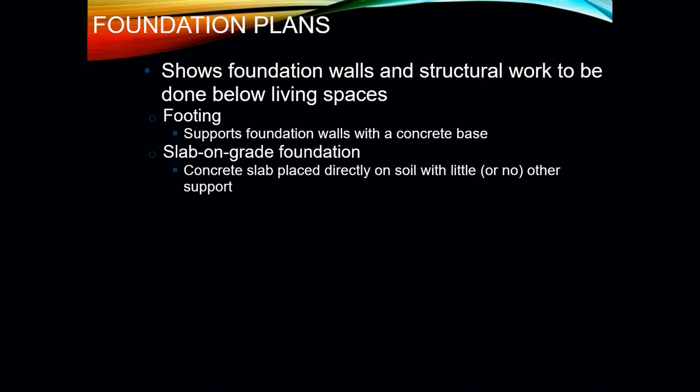Now foundation plans, obviously that's the foundation of the building. That's going to show you your walls, your structural work to be done below the living space. Obviously we're talking about basements, maybe slabs, houses that are on a slab. Anything that is below the house is going to be on your foundation plans. These plans are going to show you the footing. It's going to show you the supports that are going to be needed. If it's on a concrete base, it's going to show you your concrete slab placement.